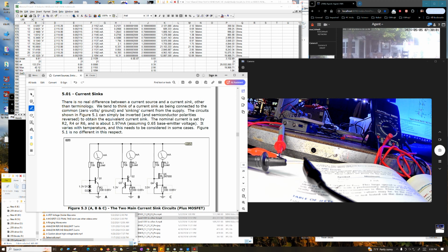That's going to equal approximately the diode voltage drop across this transistor, so it'll start to conduct if it sees that kind of current on it. All right, and basically this resistor here is just kind of a dummy load to dump excess current into it. It has some effect on the current, but overall it's pretty independent of that. It's this element that is primarily responsible for setting the current.